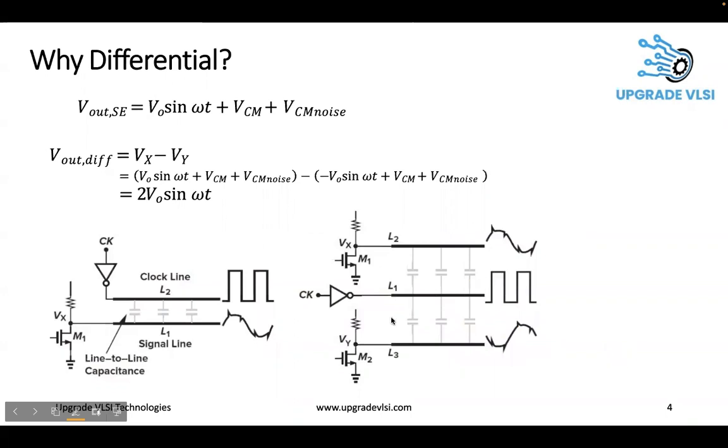So the question is, why differential signal? Here is one diagram which tells what could happen with the single-ended and what could happen with the differential signal. If you look at any IC, there will be a lot of blocks. There can be a switching block, a clock generator, and a digital circuit that does the processing. All clock and everything is routed. And here can be a power supply unit, PMU. This could include band gap, or an LDO, or a PLL. It can be anything.